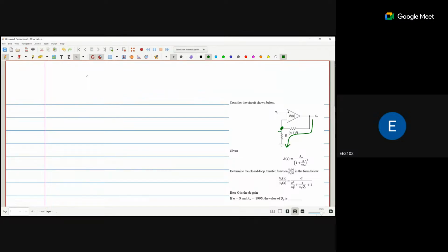So the voltage drop across this resistance from the V naught is this point voltage. If I say this is the VB, so VB is what? V naught divided by the total resistance, (n minus 1) times R plus R.